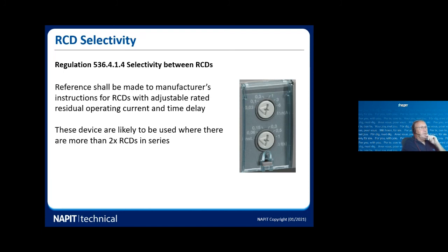And you can see that the lower dial is delta T, or time. Now this is time delay. It's not the operating time, it's the delay time. So you can see it has an instantaneous setting. The I is just missing off that picture there, INST.